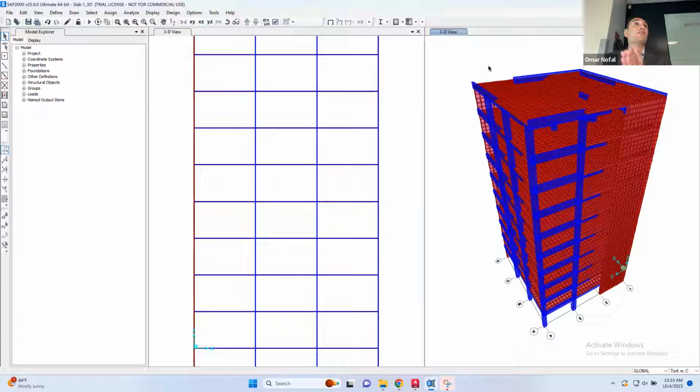I can say that this is a pure shear wall system and only rely on the shear walls, designed to take all the seismic load, and neglect the impact of the columns. However, in real life the columns are going to contribute. But the shear wall is designed so that if the columns fail, the shear walls take everything and the structure is still good to resist the entire loads. So if I design the shear wall to take all the lateral loads, then the column is actually providing additional safety.